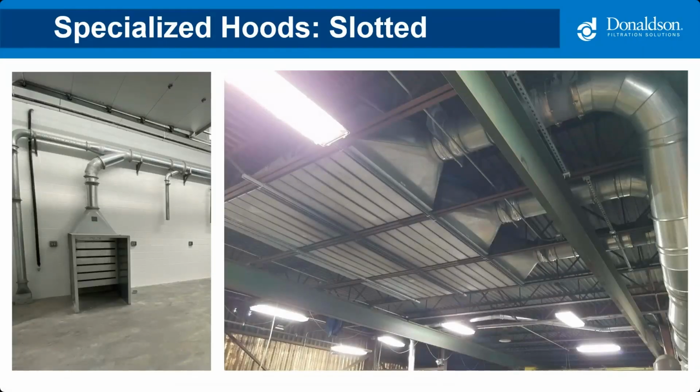These are specialized capturing hood types. This is what's called a slotted hood, and these are also common for weld fume capture. You can see in the pictures, it has little open slots which create a high velocity area where the dust or fume is directed into the hood. The one on the left is like a little booth enclosure. And the picture on the right would be an overhead fume capture system, where again the high velocity of the slots motivate the air into the hood.